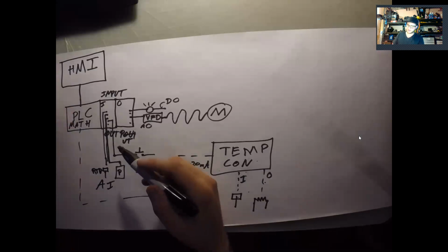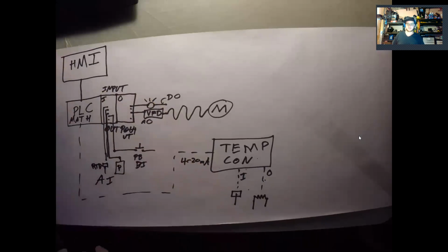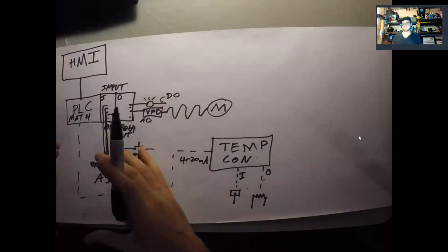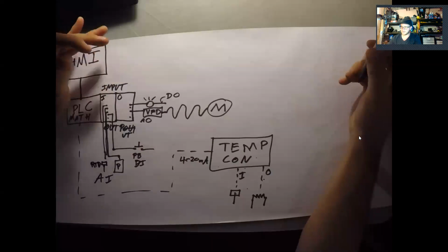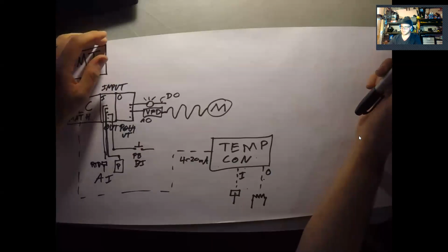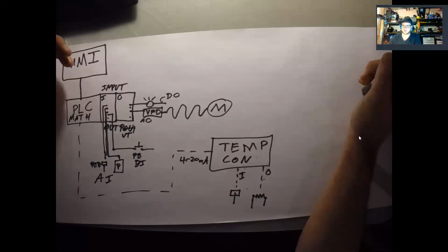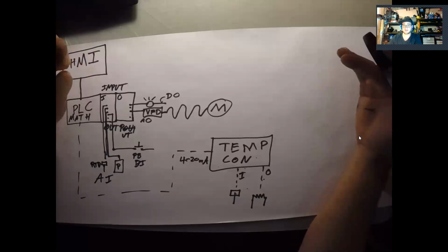And then the final connection that I want to talk about is, a PLC is generally used for kind of one system. So that might be like an air conditioner or a heater or a bank of fans or a reactive system or something, right? But usually a lot of times it'll be what's called a skid-based controller.